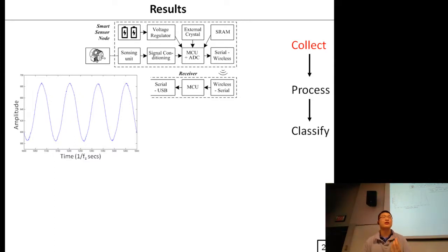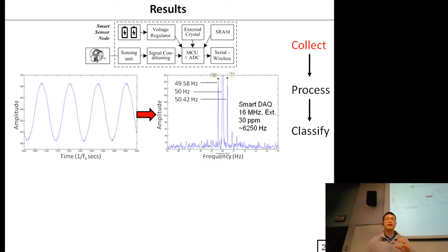How am I sure I can actually use it for fault detection? The way I validate is I collect the data, like sinusoidal data here, that's very, very slightly amplitude modulated. If I collect enough data at a high enough frequency resolution, I should see very precise differences in the resulting frequency. In this case, it's about 0.5 hertz.